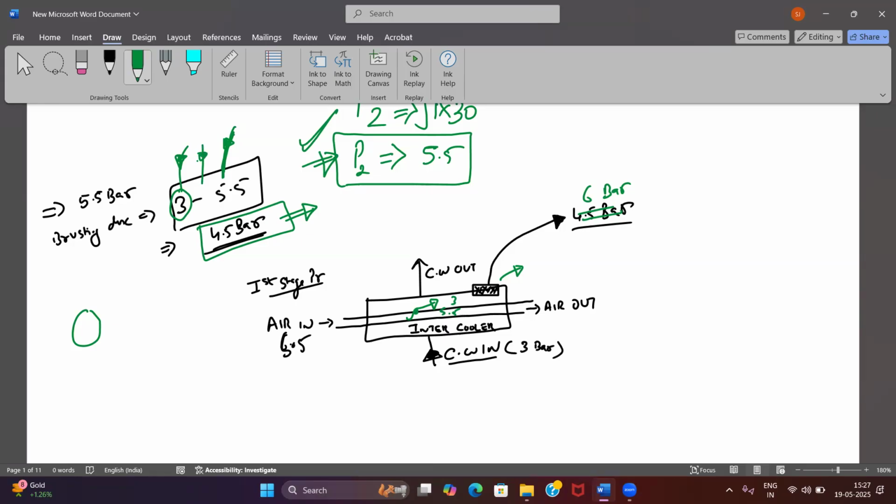Sir, at my last oral, the surveyor asked me what is the use of a bursting disk. I said we are having the intercooler and the copper tubes. If there are any holes in the copper tubes, the air may leak into the water side and the bursting disk is going to burst, releasing the pressure instead of the intercooler. So he's asking what is the main use. I answered this question, but he's not accepting. Is there any reason like that?